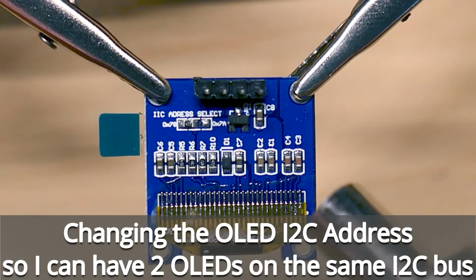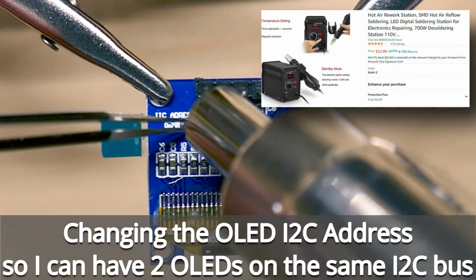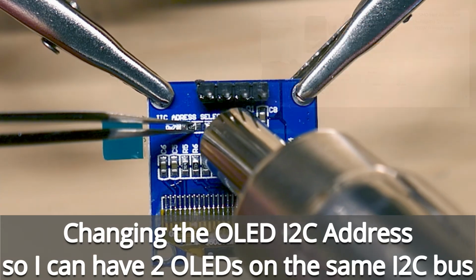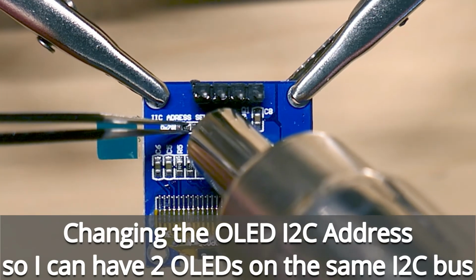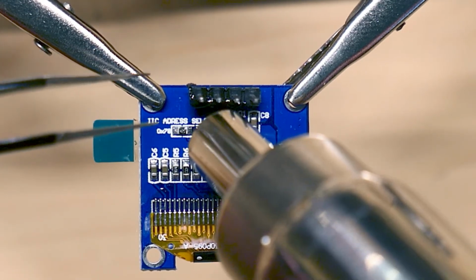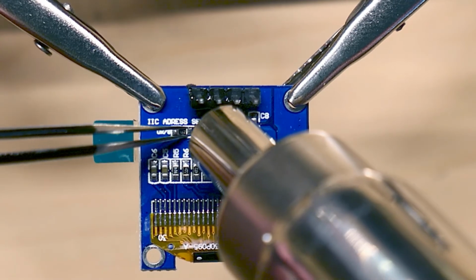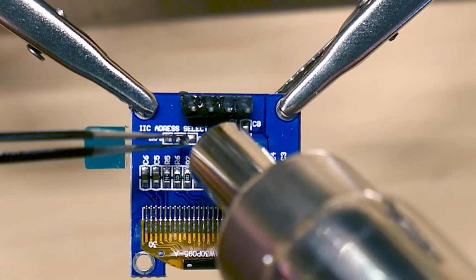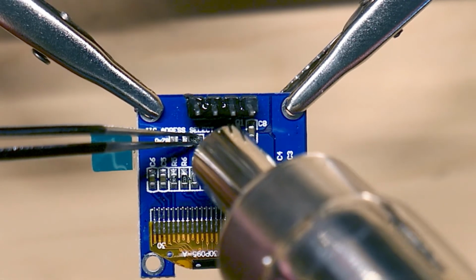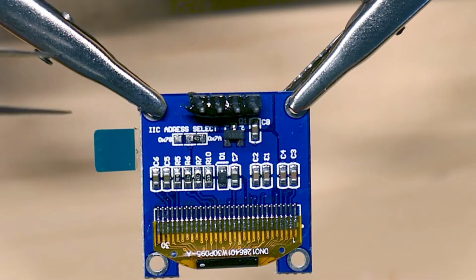I need to change the addresses for 2 of my OLED displays, so I'm using a rework gun here to heat up the surface mount resistor that switches between the 2 addresses that the OLED device supports. So just heating it up. I got the gun set to about 300 degrees. It took about 15 seconds to melt the solder. There you see the resistor moved, and then I can just place it in the new address location, heat it up, and the address has changed.